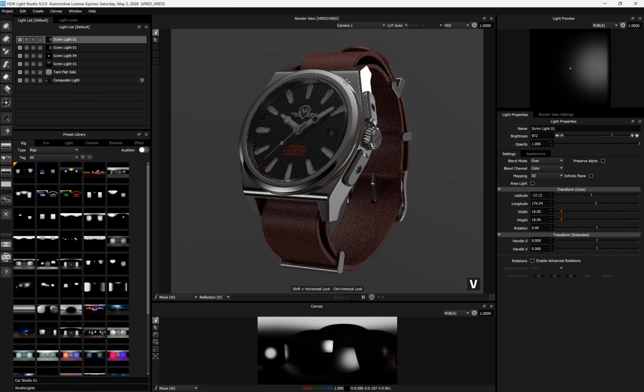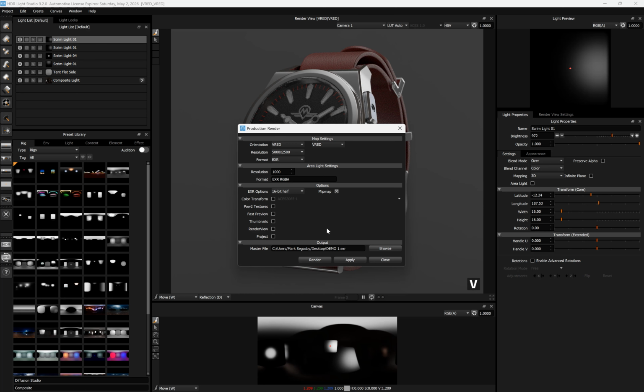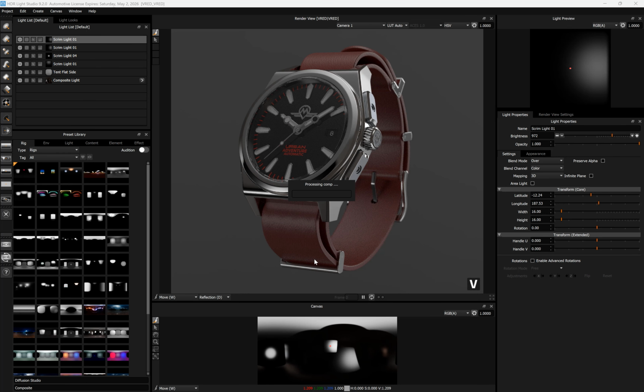And then the important thing is, at the end of the editing process, we must generate the HDR again. Press render. This will leave the scene, the VRED scene, using a map on disk that's high quality. We don't want to leave it with the low quality live map.